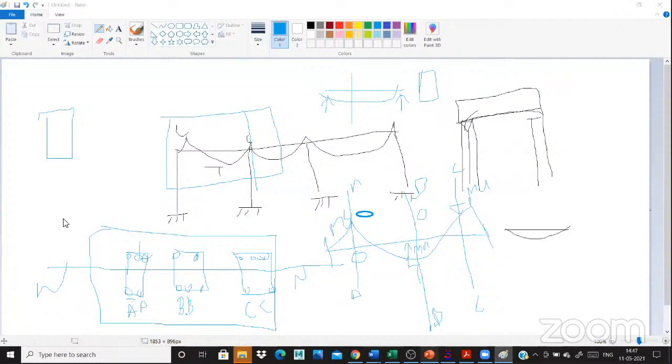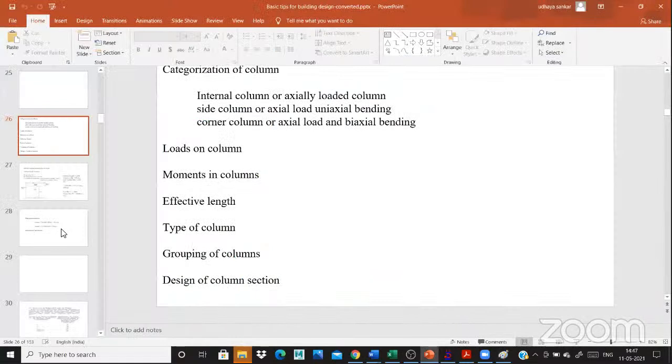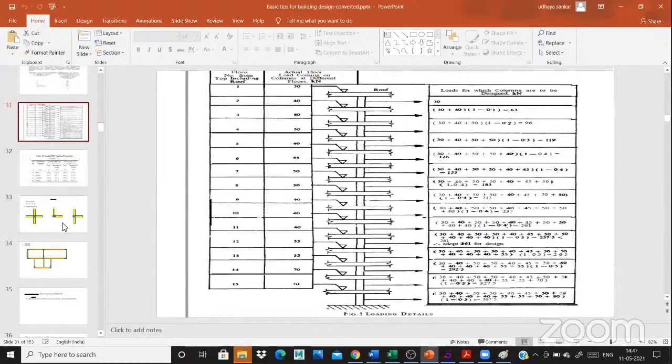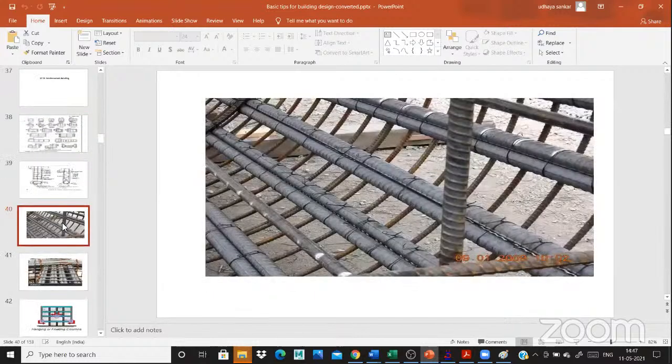This is a column. Yesterday we discussed this type of column. Another one is bundle bars. As per bundle bars, the construction reinforcement uses a larger number of bars. You can bundle with two bars. The design is in SP 16, and how much spacing will be provided for the bundle bars and others is provided in SP 34 rules. Now understand how to provide the bundle bars and others.